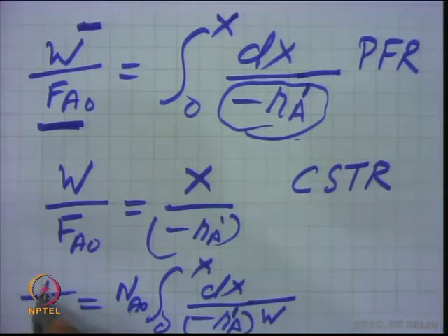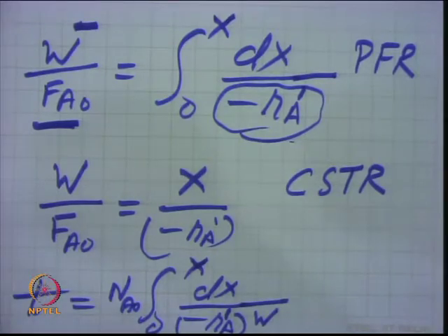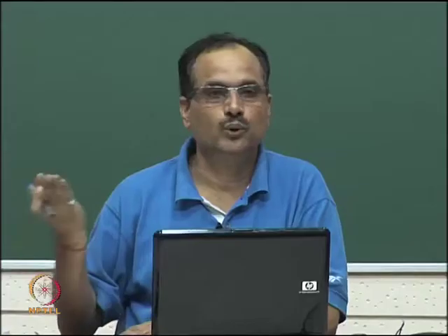So, here t is written in terms of that, because the batch is an unsteady state operation and conditions change with time on stream. So, this is the time required for a given conversion in a batch with the moles which have already been kept, because in the batch there is nothing like a continuous flow. The reactants are fed inside, and then after a certain time we get the product and we measure the conversion by analyzing the components.